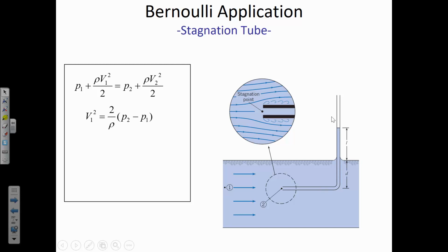The reason why the tube has pushed the water up above the free surface that the rest of the water is at, here we can see these little dash marks that are meant to represent the rippling sheen of water. Well, the water level rose a bit higher inside of that tube that's open to the atmosphere. It's not because there's suction in the tube. This tube is open to the atmosphere, but this rise here, L, is because there's additional pressure at location 2.